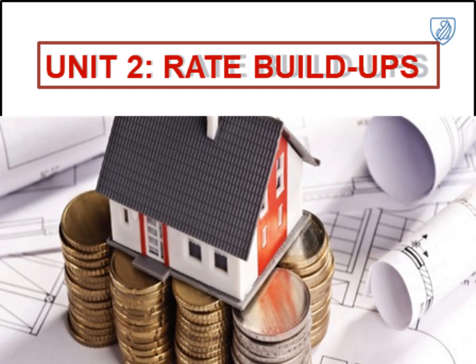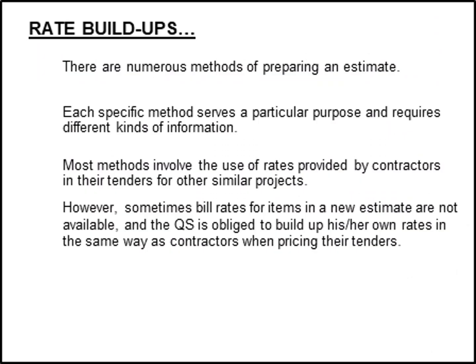So for your elemental estimate, this goes hand in hand with your elemental estimate and is a way to approach it. The example that was provided will give you the structure, but you always have to refer back to your elemental guide on what is included and what's not included in your elemental estimate and subsequently your rate build-up. The main thing about rate build-ups is you're taking existing rates and amending them to be in the correct unit for your estimate.